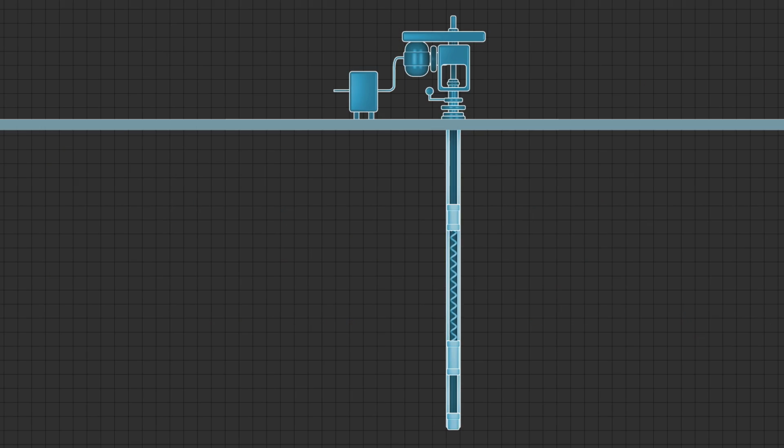So how does a progressive cavity pump work? A PCP pump or a screw pump is essentially like an auger that draws the oil from 4,000 feet below the surface, and it takes about 4 hours to get this heavy crude from the bottom to the top. During a recloser operation, the drive in the pump would stop, and it would take about 4 hours to backspin the 8-inch shaft, and then 4 hours to pull the oil back up to the top.